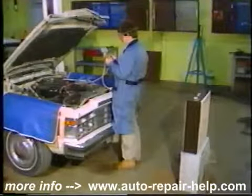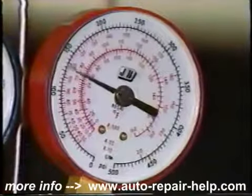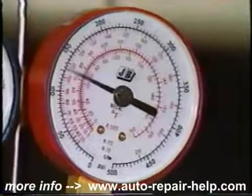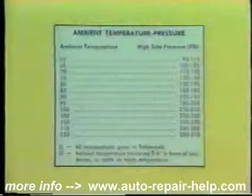Read the high pressure gauge. The proper gauge reading at average humidity can be determined by taking the ambient temperature and cross-referencing this reading to the pressure scale on the chart.